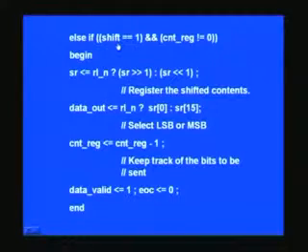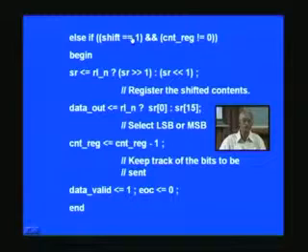Next step is if shift is asserted and also the counter is not 0, which implies that it has been processing, sending the information. This is once again an AND symbol, and this is a total logic expression, and therefore you see 2 equal to. If you put 1 equal to, it will complain. And if it is not equal to, you can use it in this fashion. We have already seen here. And mind you, you should not use the tilde sign here. In logical expressions, only this exclamation mark is to be used.